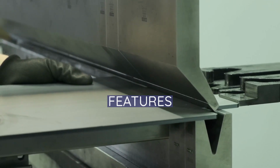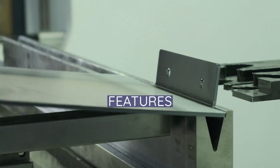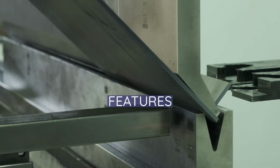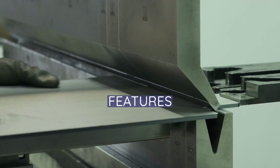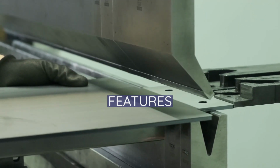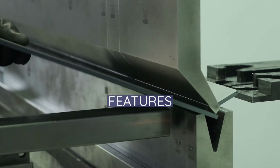NIAflow provides a graphical interface that allows users to create process flowsheets by dragging and dropping equipment modules. The flowsheet can represent various stages of mineral processing, including crushing, grinding, screening, washing, sorting, and dedusting. Each process unit is backed by a calculation model that simulates mass and volume flows, particle size distribution, moisture content, and other critical parameters.